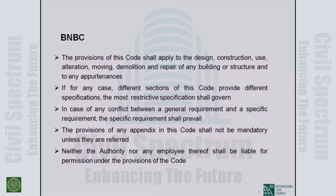If for any case different sections of this code provide different specifications, the most restrictive specification shall govern. For example, if there is a debate between part 4 and part 8, part 4 being fire prevention and part 8 being HVAC and other things, there are sometimes conflicting data because different people write them. In that case, the most restrictive specification will govern.